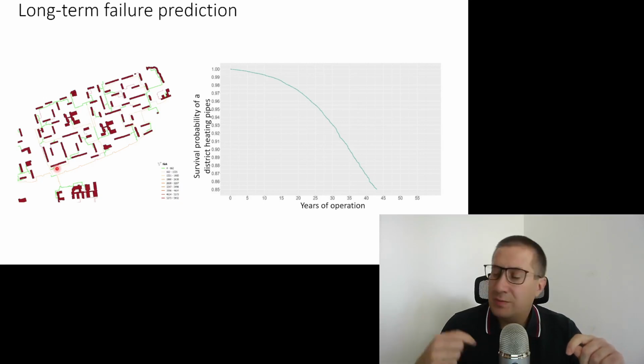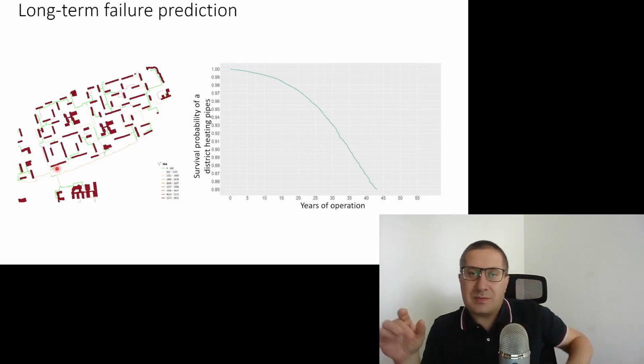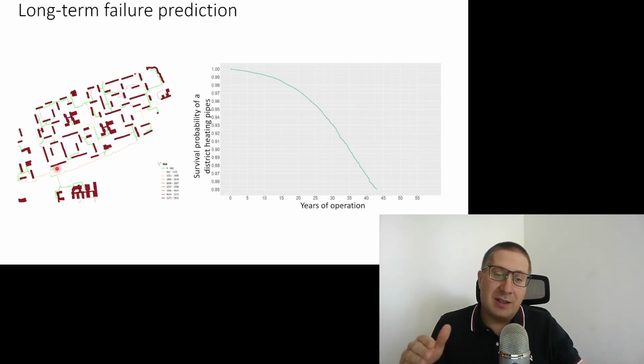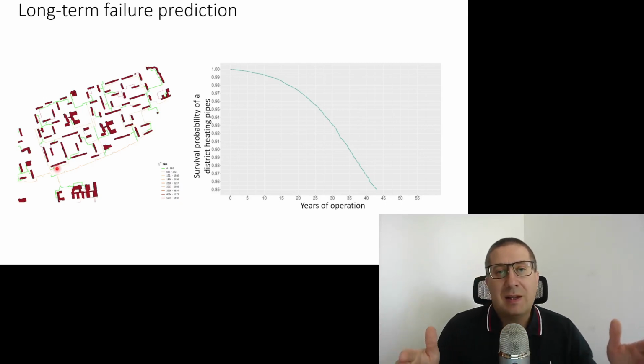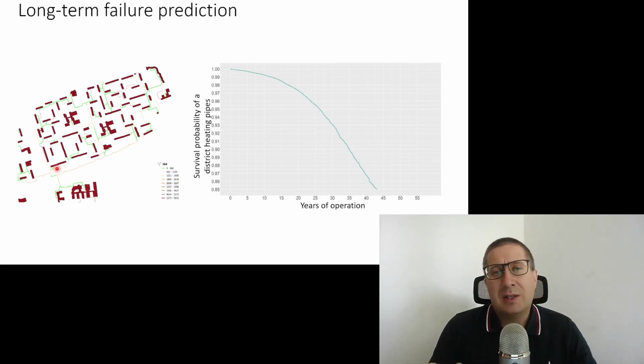And we took many parameters of those pipes: diameters, material, when they were built, if they are under or overground, what is the type of isolation, etc. The number of failures in the history, right? And of course, the age. Based on those parameters, taking into account historical failures, we were able to create an algorithm that predicts the risk of a failure.